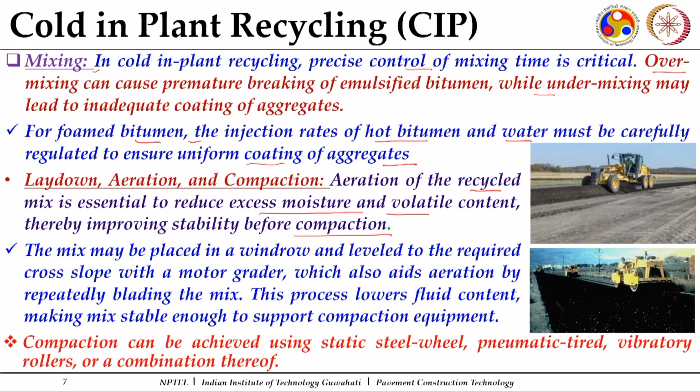Here you can see the mix is placed in windrows and leveled with the help of a motor grader, to bring it to the camber or the cross profile. So, the mix may be placed in a windrow and leveled to the required cross slope with the help of a motor grader, and this process also helps us to do some aeration to a certain extent.